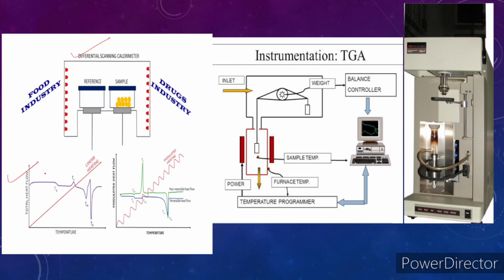What are the components of the DSC graph? On the x-axis, we have the temperature or the time. It shows how the heat flow changes as the sample is heated or cooled at the controlled rate. On the y-axis, we will measure the heat flow in watts per gram or milliwatts. It indicates how much heat is absorbed or released by the sample during the test.